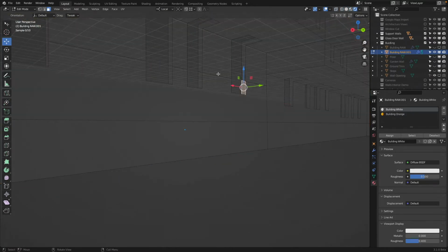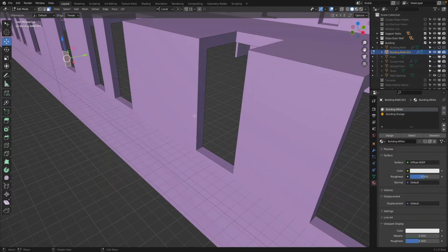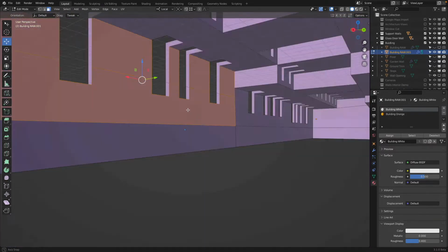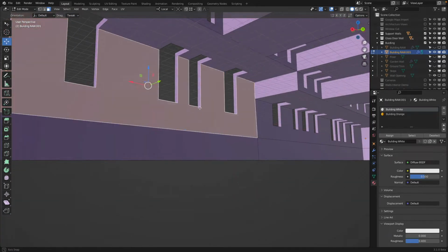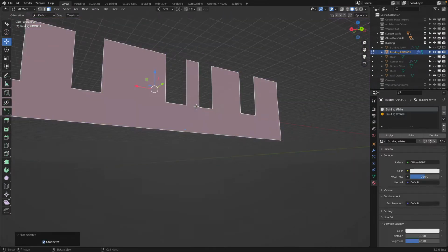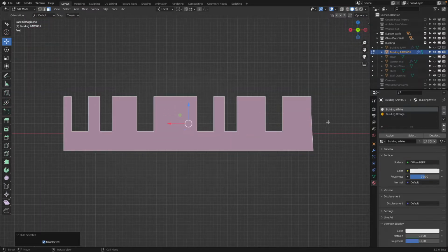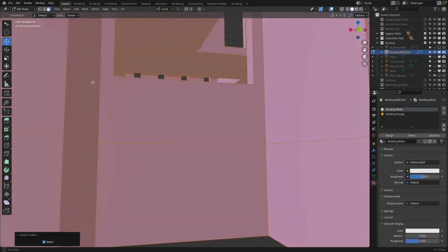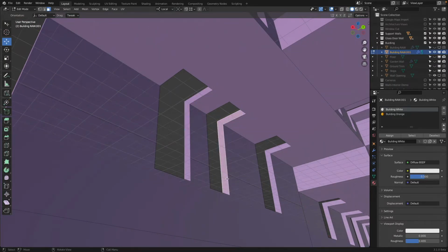But as we can see also here, these cuts went through there too. Let's see. Yeah, it did it. Now and then you see how they're coming up there. So how can we maybe prevent this? I simply press Shift H. I hide everything else. Go to this view, press K, click X, click and enter. Alt H. So you saw by hiding the other geometry, it didn't really cut it.